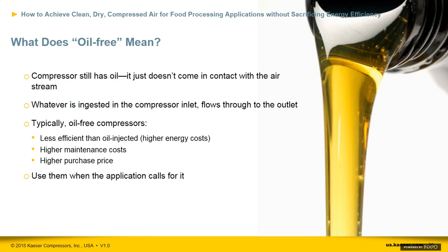So what does it mean to have an oil-free compressor? It doesn't mean that there is no oil in the compressor. It means the oil doesn't come in contact with the airstream in normal operation of the compressor. Keep in mind, whatever is in the ambient air will still be ingested into the compressor inlet and flow through the compressor into your piping system. Filtration and drying are still necessary for clean, dry air and an oil-free system.